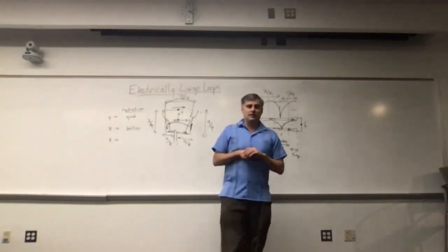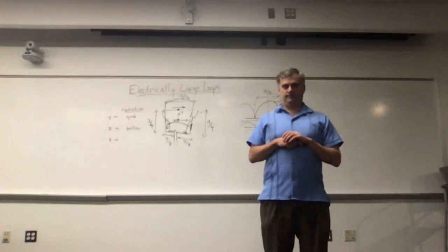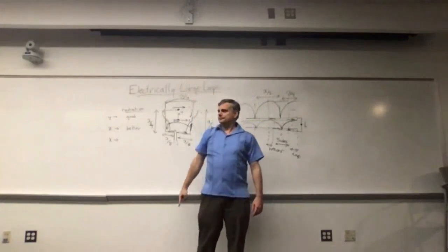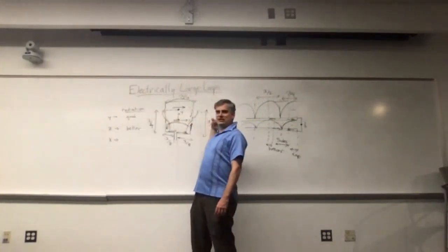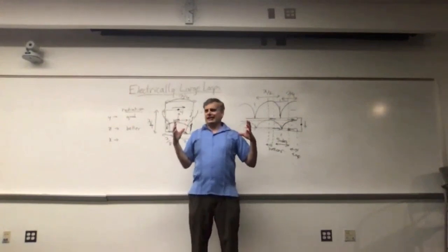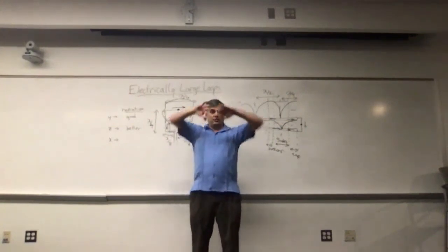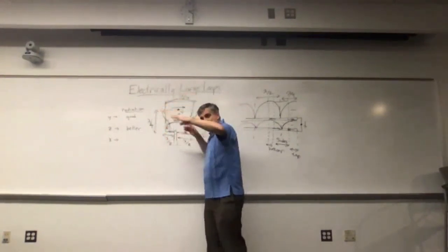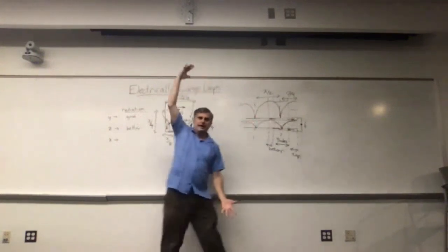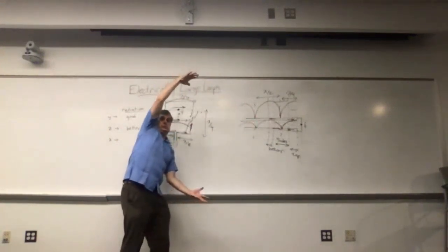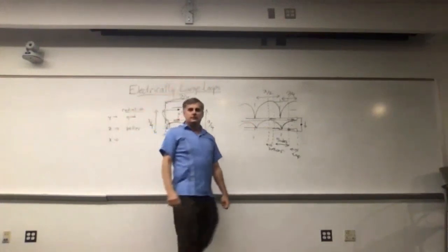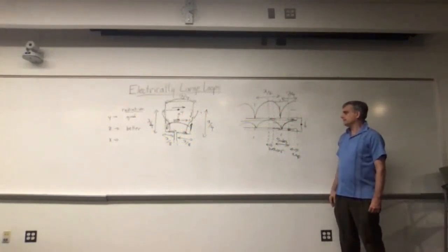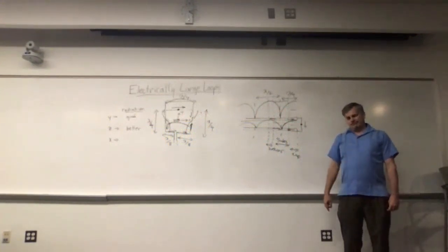Jared? So a 3D pattern would look like a donut? Yeah, that's right. So it would be an oval, and then you would definitely have nulls in these two directions. So it's almost like an electrically short dipole with the sine squared pattern, except turn it on its end, turn it on the side. So the nulls are in this way, the donut's in this way, and then take this dimension and go about 50%. Very good mind jam, visualization jam.